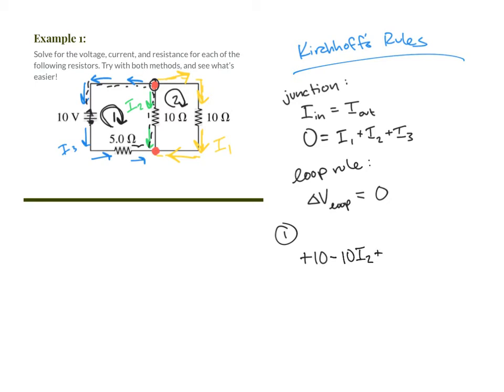So that potential is IR, V equals IR. So you add 5 ohms times the current there, which is I3. And then as you continue around the wire, you're back to the point you started at. And the whole voltage around the loop has to add up to 0 because you're starting and ending at the same point, so you can't have a potential difference.